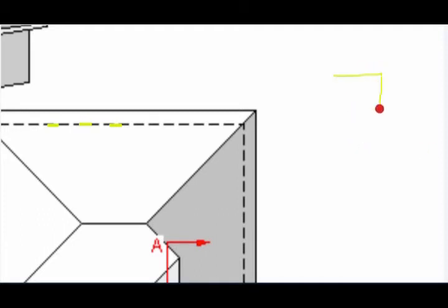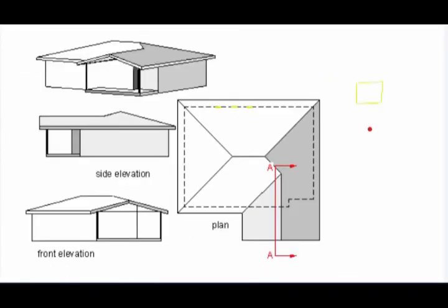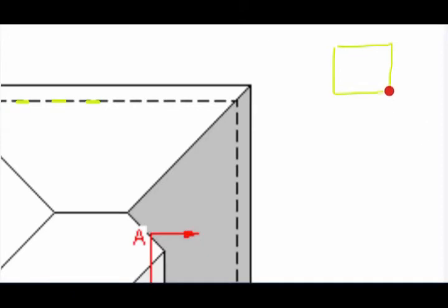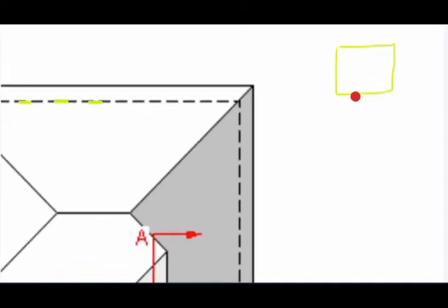So you have a plan, and here is the entrance, okay? Here is the entrance in your plan. And in order to draw this entrance, let's put it at the center. Apart from those 80 centimeters that you are going to offset on each side, you should also offset 80 centimeters from this side because it is the entrance, it is very important.